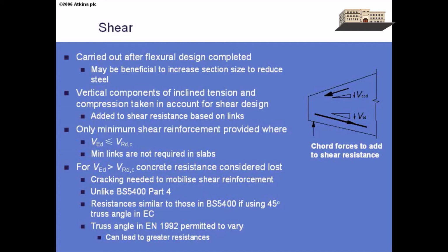But if we have a strange little fish-bellied shape like that, this is an end support, and we've got the tension reinforcement here and the compression field here, then the compression force and the reinforcement force are both actually carrying some of the shear. And so, depending on how you look at it, we can either deduct those components from the applied shear, or we can add them to the shear resistance. And that's just pure statics. We've got shear force on the end, and it's obviously been carried by those components in part.